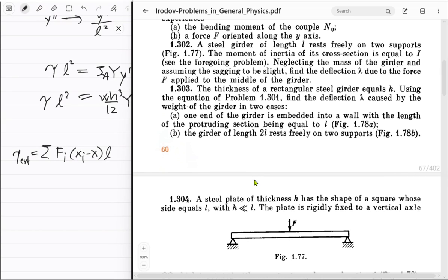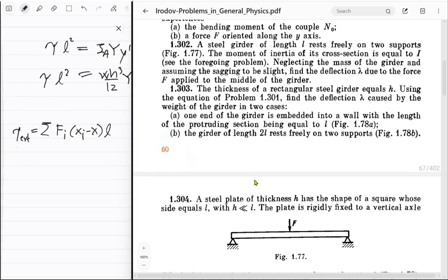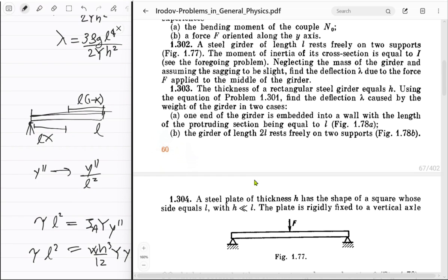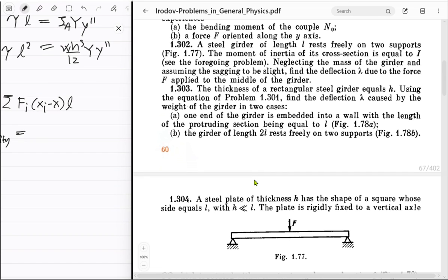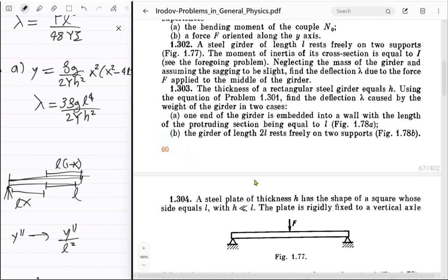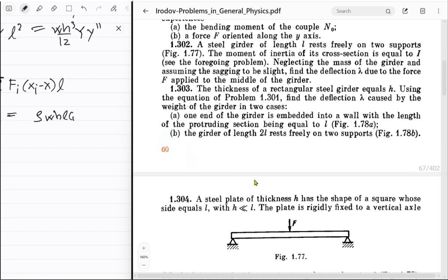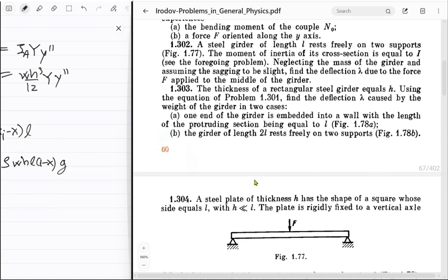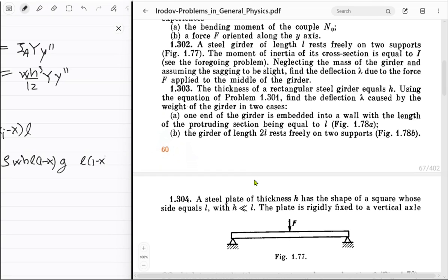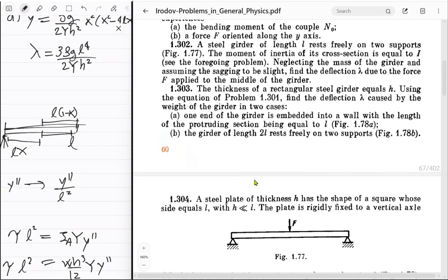Okay, so that's awesome. And torque, gravity, how are we going to do that? So it's this mass, right? The mass is just rho W H times this length, which is L times of 1 minus x. So this times g, that's our weight. This will be at L times of 1 minus x upon 2. That's our arm length, right? And it's just going down, so it's good. It's clockwise.